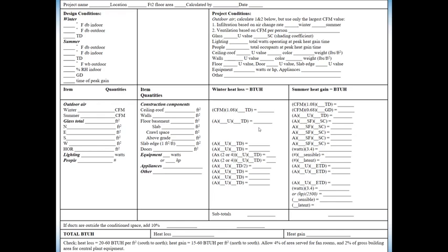All those U values are going to come from, what was the U value? It was a conductance value. It is nothing but 1 over R, which is resistance, resistivity for the material. So we are going to get all those, perform all those calculations, and after that we are going to do the load calculations. And in the design conditions, we know the indoor and the outdoor winter temperatures.